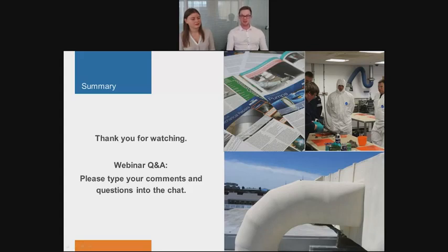For a wide variety of applications, then yeah, you could use Belzona, but it depends, like you say, on the upset conditions, abnormalities. So maybe there's a big temperature spike, or they put a really, really nasty chemical through the system every week. So again, it's really important that you get a full list of everything that might happen with the system. Even if it doesn't happen, it's better to know and plan for it than it is to find out 2 years later that your Belzona or your repair has stopped working because of something that was missed at the initial stages. So yeah, having that list of conditions that you expect is key in making sure you spec the correct material for the type of repair that you're doing.